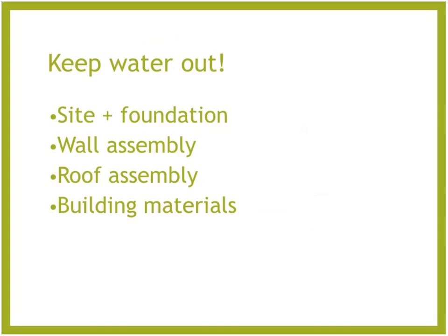So looking at site and foundation, keeping water away from the foundation through slopes, through downspouts, through well-draining soils, sandy soils, depending on that. Again, keeping that water away from there. And also, this plays into basements.